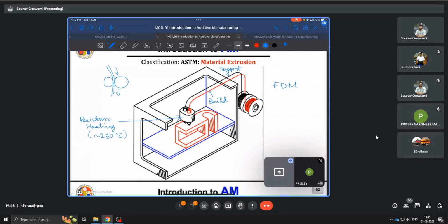And of course, as you can notice, the scanning speed, that is how fast this head moves, also plays a key role, because what you're depositing is, say, a semi-solid trail of liquid. So if you go too slow, you end up overbuilding in the same regions. If you go too fast, maybe you miss certain regions.